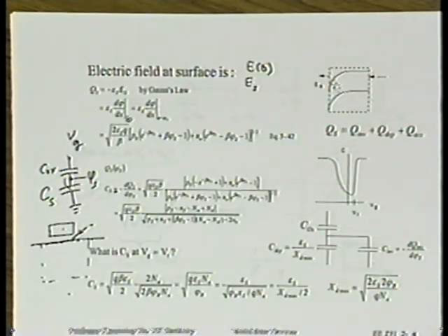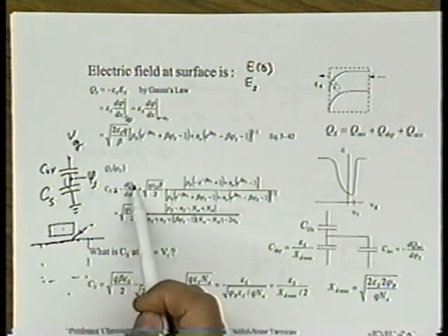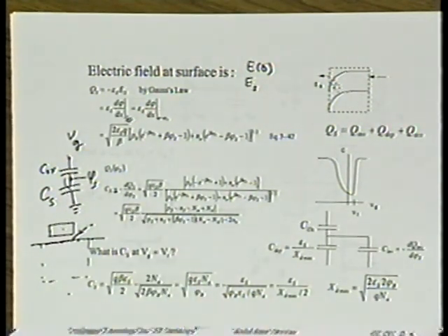Don't think of this physically as some depletion layer or whatever. It's a much more general concept than that. If you have to supply charge in order to change the potential at a point in the device, you're dealing with a capacitance, all right? And what's the value of the capacitance? It's the ratio, or differential, of that charge you have to supply with respect to the potential of that terminal.